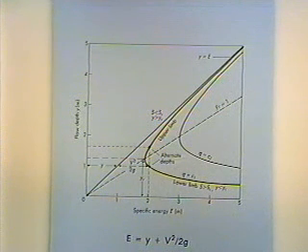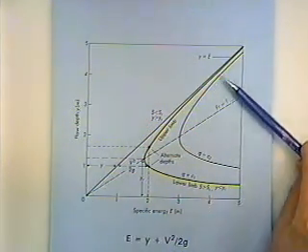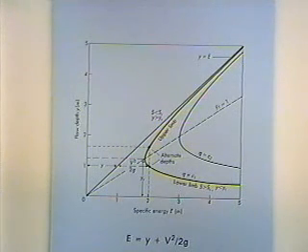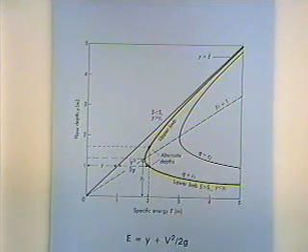Now, at some point, the 45-degree line, we're asymptotic to that, and we can call these alternate depths. We talk about hydraulic jumps, and we will a little later. These will be pertinent to us then.